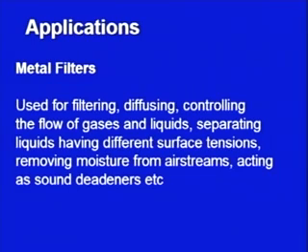Then coming on to the application areas of powder metallurgy. Now, the first application is metal filters. What are metal filters? Metal filters are used for filtering, diffusing, controlling the flow of gases and liquids, separating liquids of different surface tensions, removing moisture from air streams, and acting as sound deadeners. So, metal filters can be made.